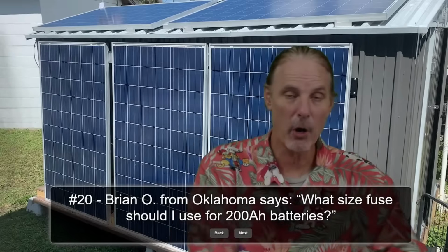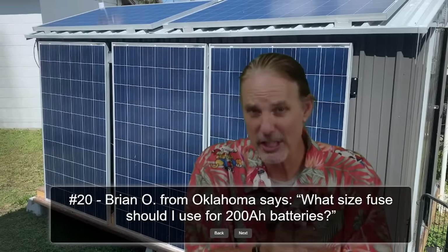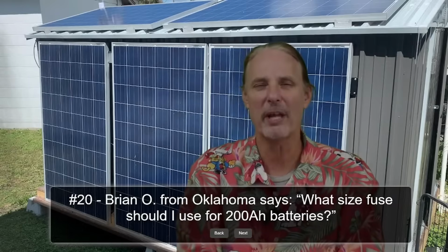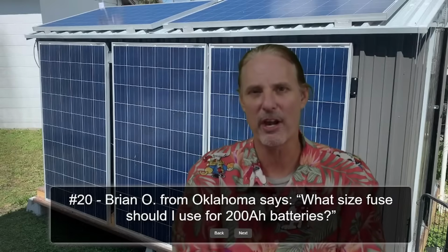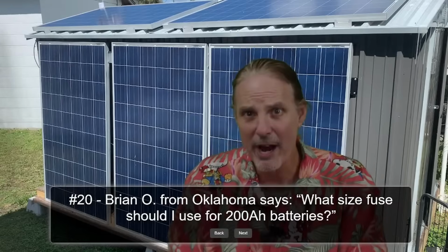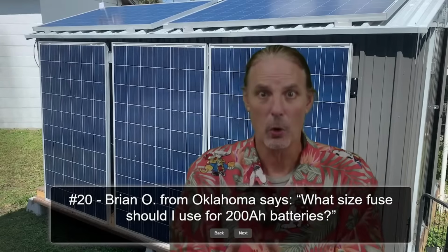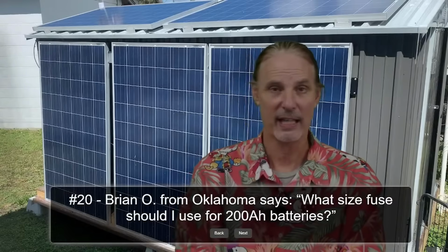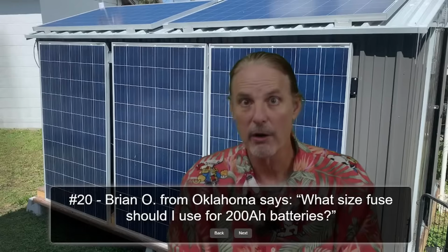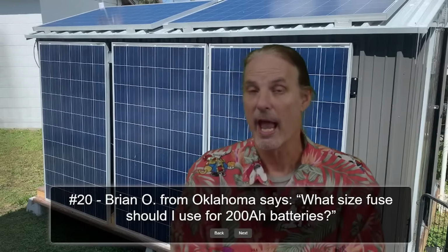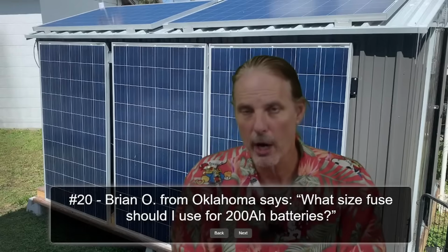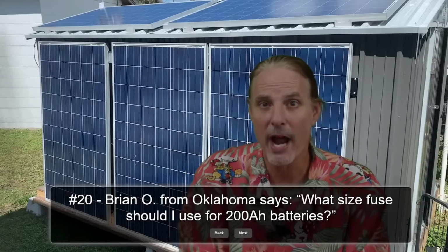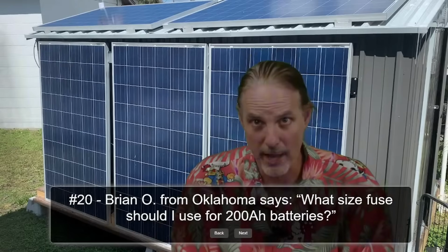Now, the second part of the equation here is usually the most important part, and that is fuses and breakers most of the time are there to protect the wiring from melting or causing problems. And that means that if you have, let's say, 8 AWG or 8-gauge wire, and you don't have larger wire, then you're going to want to build the fuse to protect the wire and the circuits around that wire.